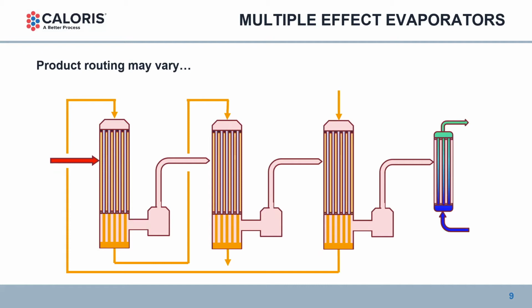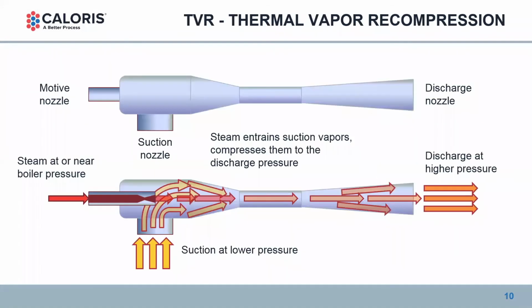And another example would be if we're evaporating, say, permeate. As we build concentration, the lactose can start to reach its crystallization point, and we can suppress that crystallization point by keeping it hotter. So then we build concentration at the higher temperature effects. So that is the summary of what I wanted to get into in the concepts of multiple effects and direct steam heated as the base point before we now get into TVRs.